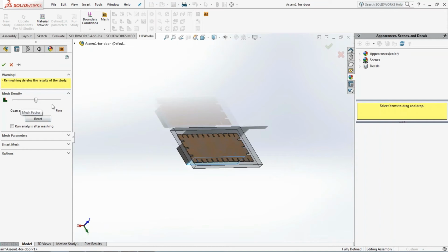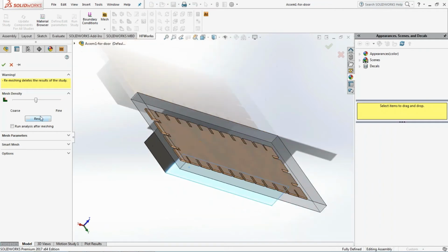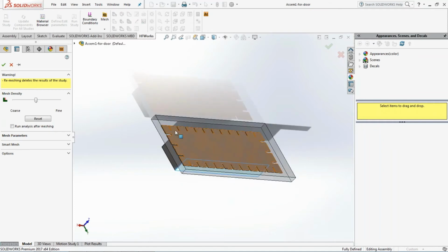So the antenna designer or the RF specialist who is doing this, depending on the accuracy that he needs, he can define the size of the mesh, and he can customize its accuracy and compromise. Okay, I don't need a very heavy study, but I would like to have a coarse mesh. Or no, I don't mind to have a heavy study. I need very, very accurate results. I can make a fine mesh.